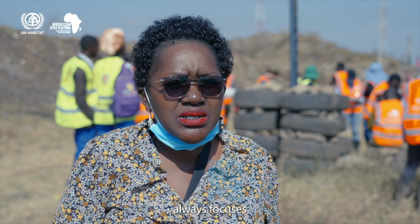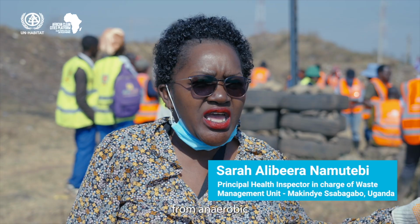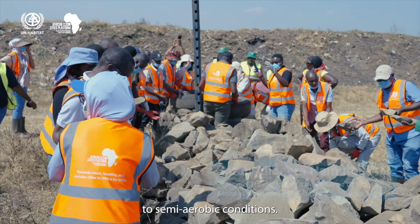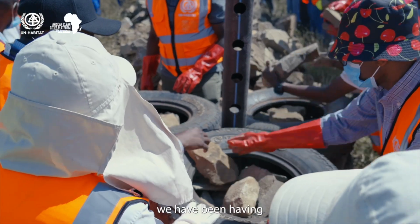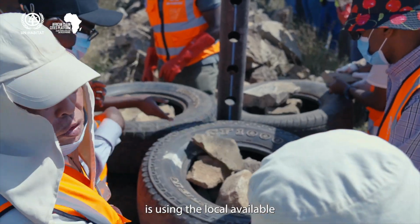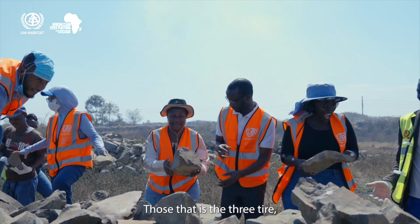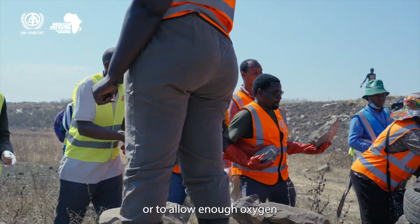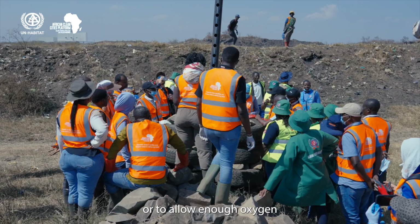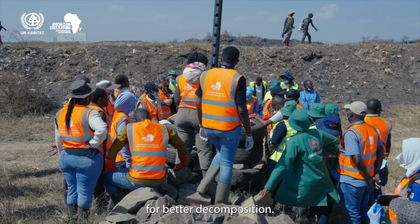Fukuoka method always focuses on stabilizing the waste from anaerobic to semi-aerobic conditions. So the demo we have been having is using the local available, the most cheapest way. That is the 3-tier, which is 3 down and 4 up, plus a vent, all to allow enough oxygen to get down the waste for better decomposition.